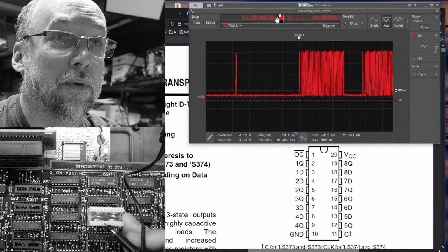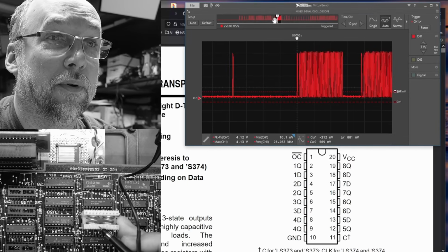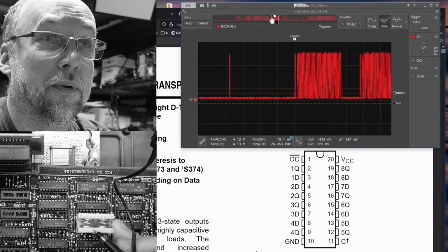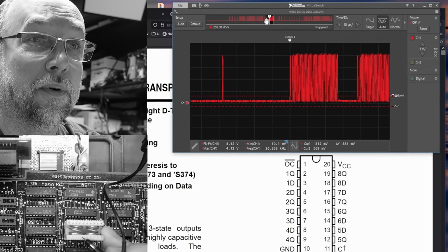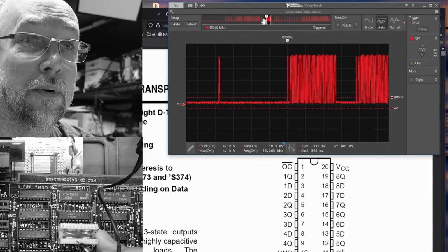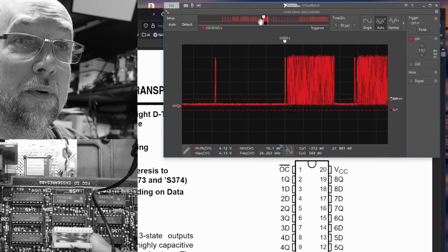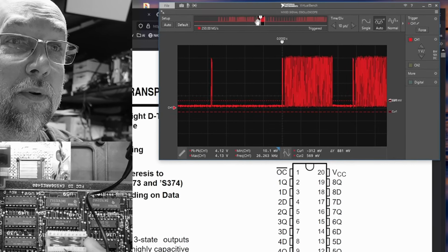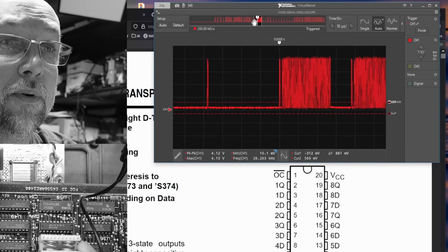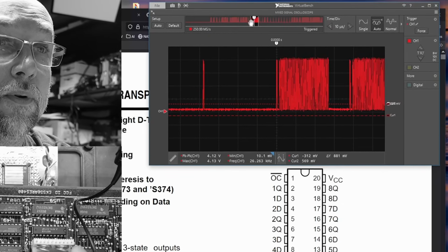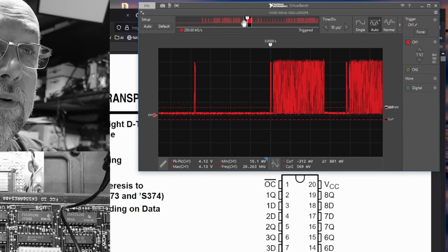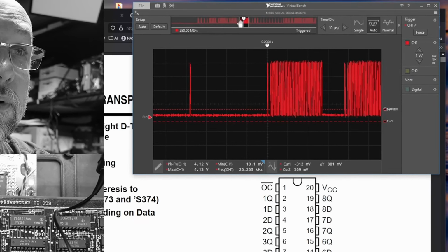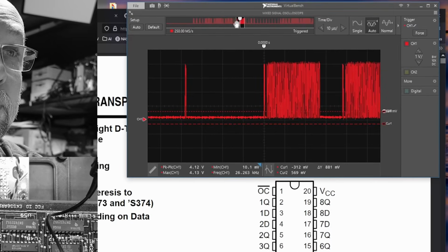Right, I'm editing the video and I see exactly what happened here. The test pattern I was displaying when I was testing the inputs and outputs of the bad chip, we had the 640 by 200 grid pattern up. And that was obviously the wrong pattern to be testing with, because here I am testing the bad pin, and the only time that clock signal leaks through onto this is when the signal is up at 5 volts. But most of the time when we're looking at the grid pattern, it's down at ground, which is why I didn't notice the pulsing that was happening when it was up at 5 volts.